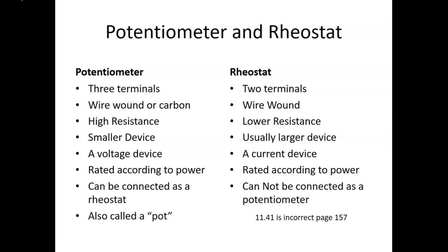So the main big ones here is that potentiometer is a voltage device, rheostat controls current. You can connect a potentiometer as a rheostat, and that they have 3 terminals versus 2 terminals. I'll go ahead and pick that information out for you there.